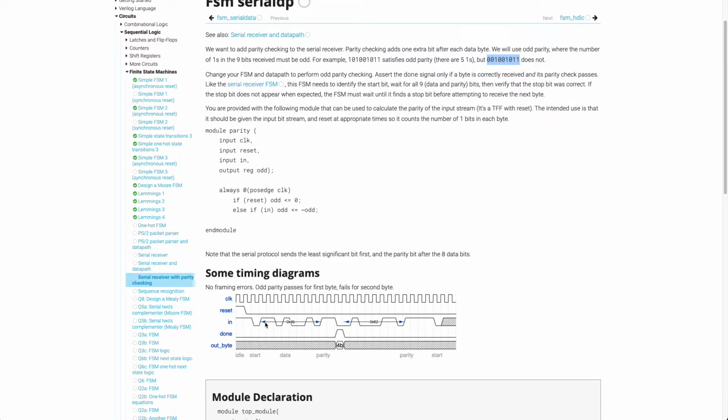So I take this, and then each cycle, in the data, I would use this to see if it's odd or not. And so I find a stop bit here, and I output the data without the parity bit here. Okay, so high level, our count is 9 instead of 8 now. So this would be 8 and this is 9.